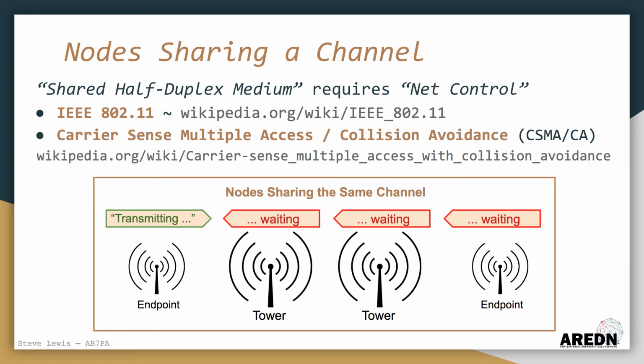A wireless network is what's referred to as a shared half-duplex medium, so only one station should transmit at any given time. In that sense, wireless operations are similar to other types of amateur radio transmissions. If 2 stations key up their transmitters at the same time, they'll interfere with each other to the extent that neither of them is going to receive the other's message.